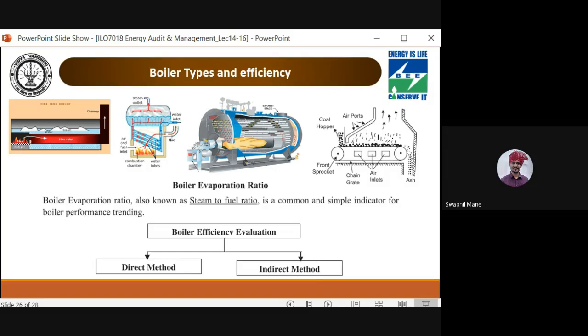Okay. So coal is fed at one end of the moving steel chain grate. As the grate moves along the length of the furnace, the coal burns before dropping off at the end of the ash pit. So in this type of boiler, some skill is required when setting up the speed of the grate or air dampers or baffles, to ensure a clean combustion. Otherwise, what will happen is the unburned coal will be passed into the ash pit.